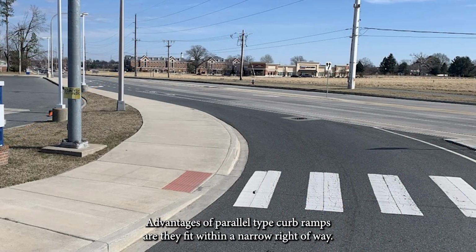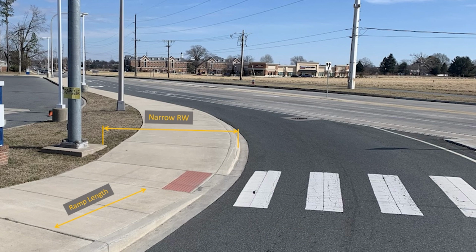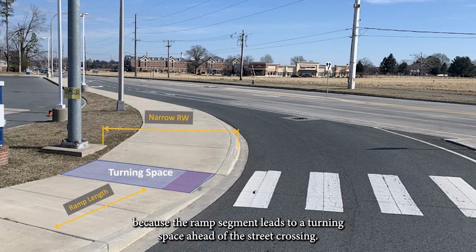Advantages of parallel type curb ramps are they fit within a narrow right-of-way. Parallel curb ramps can be easily lengthened when required to chase grade, and individuals with visual impairments find them easier to detect because the ramp segment leads to a turning space ahead of the street crossing.